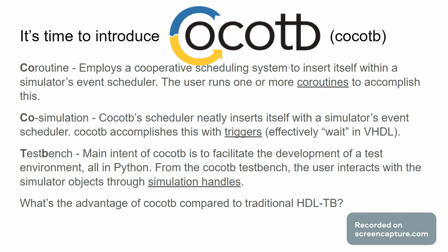This is a good time to mention cocotb. Cocotb stands for coroutine co-simulation test bench. Coroutine refers to the fact that cocotb incorporates a cooperative scheduling system to insert itself within the simulator's scheduler. I'm really going to drive home this idea, but the scheduling system of cocotb effectively makes cocotb a process within the realm of VHDL.